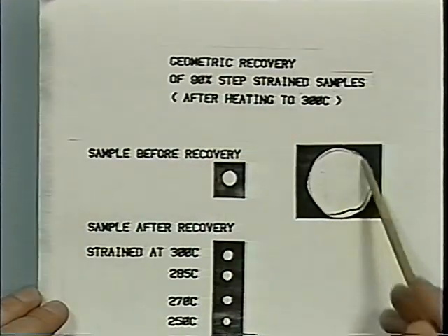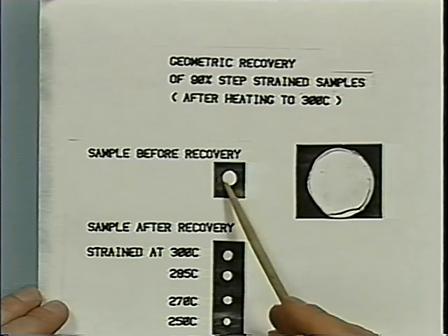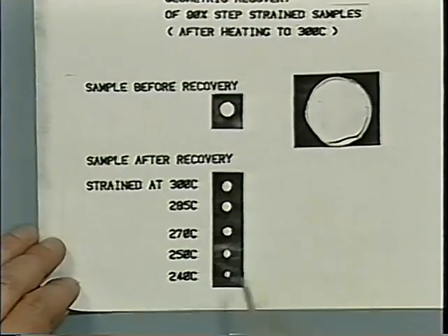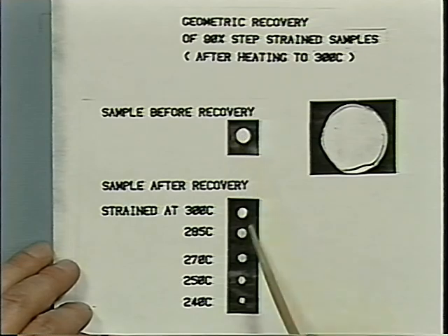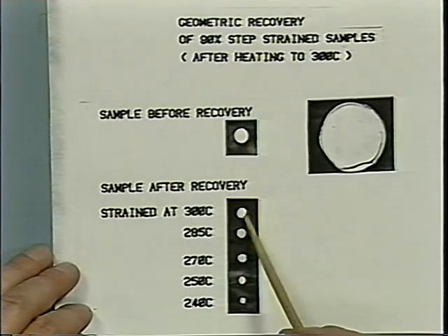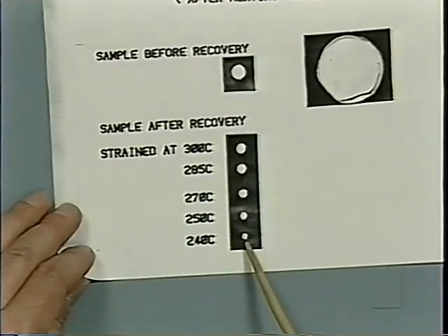So this is how our sample looked after squeezing it. It was very flat, and from this flat piece, a small sample had been taken, and then it was exposed to different temperatures. Depending on history, this sample shrunk to this dimension or to any of those. And in some cases, it shrunk down to nearly its original thickness. So at this point, I would like to break and continue with the thermal history of the material. Somehow rheology is very dependent on the thermal history, and we have to discuss that in greater detail.